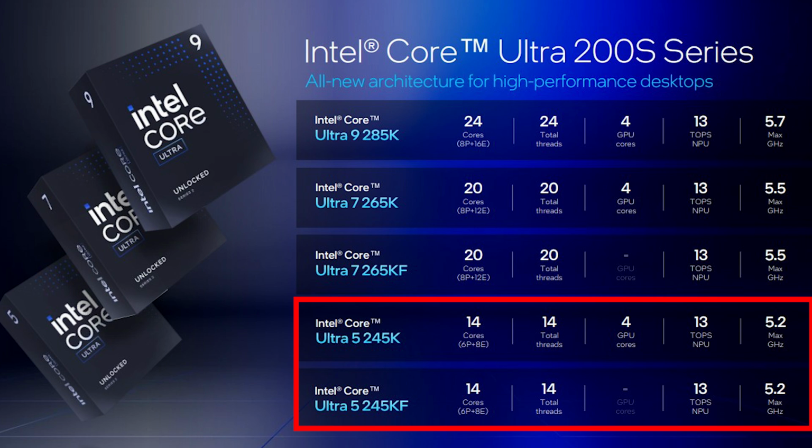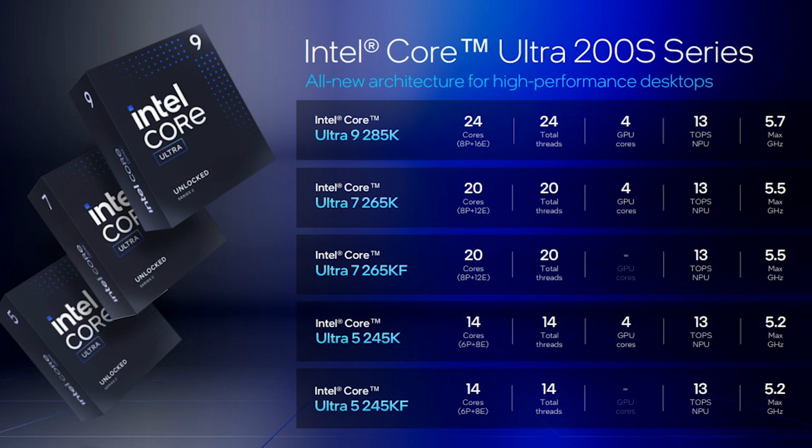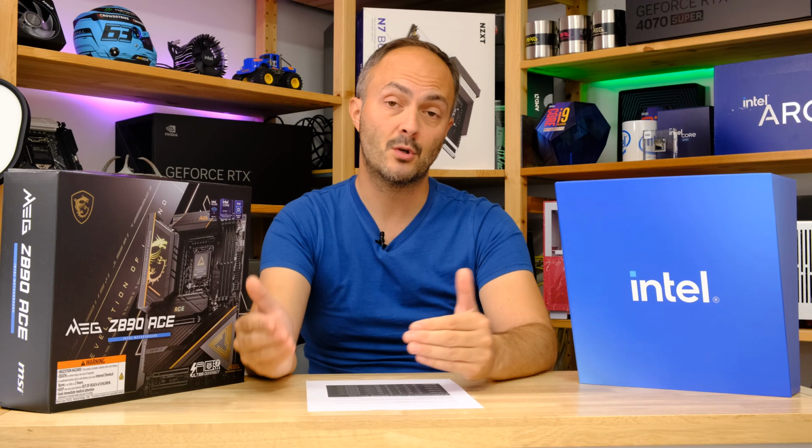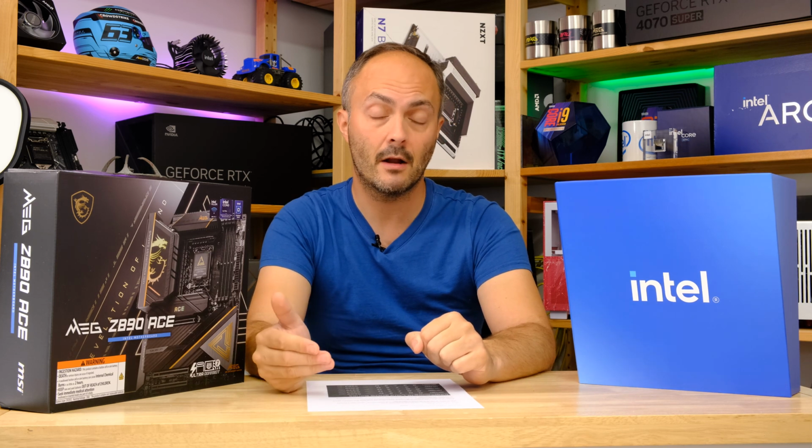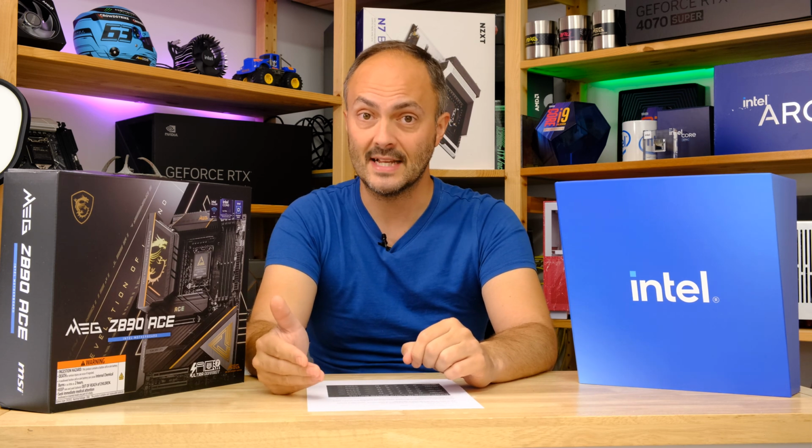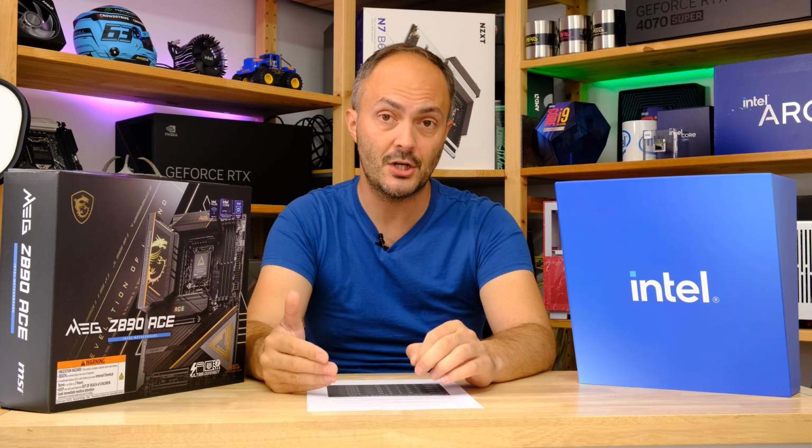Now, moving along the specifications, and we'll get to the pricing in just a second. The cores are the same, but what we don't have this time is hyperthreading. So Intel has ditched hyperthreading, and its reason for that is essentially that the makeup of the hybrid core architecture, with E cores making much more of an appearance here, not in terms of numbers, but definitely in terms of their performance, which we're going to get to in a minute. They're just not seeing the benefits from hyperthreading that they're used to in terms of how it balances out power consumption and performance. So it's already ditched it on its mobile parts, where obviously any kind of reduction in power is very significant. Less so on the desktop, but it still feels that ditching hyperthreading is the right way to go.